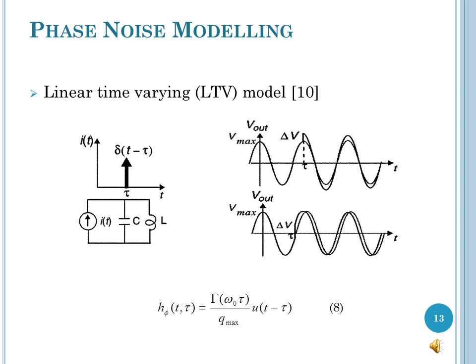It was observed that if the impulse coincides with the maximum of the voltage, the amplitude increases abruptly, but the phase superimposes with the pre-existing oscillation, and thus the timing of the zero crossings does not change. An impulse occurring at any other instance is seen to cause a change in both amplitude and zero crossings in the oscillations. Therefore, an oscillator is basically a linear time varying system with periodicity.